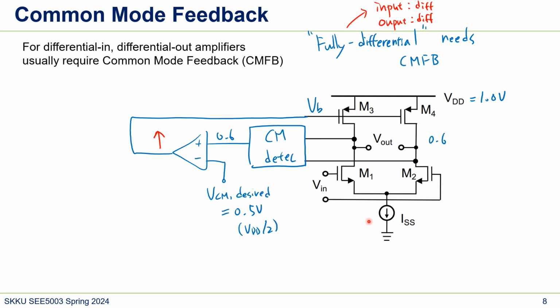So the PMOS tries to flow less current, but we do have this ISS current source, right? So VL should go up. Because this change, this increasing change, brings VGS3 down, right? Does it make sense? If the voltage at the output of the amplifier increases, VGS3 decreases, right? Because this is PMOS, VGS is here, plus minus VGS3.